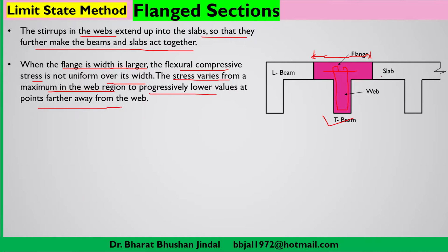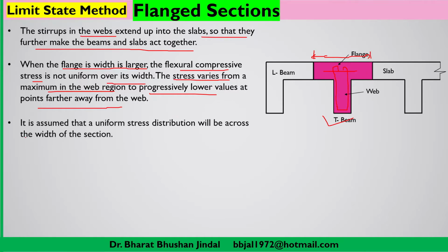That means if you draw the stress diagram, it will not be uniform if the width of the flange is sufficiently large. Here we assume a uniform stress distribution across the width of the section for simplicity, otherwise it would be difficult to analyze the section.